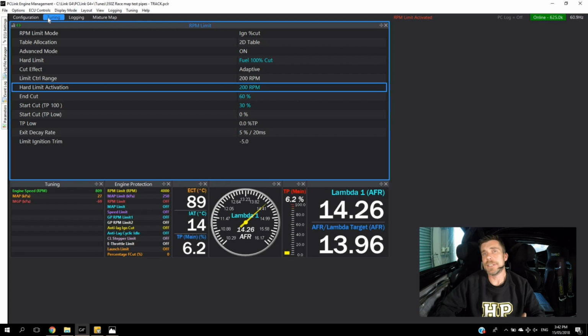So in this instance, it's quite typical to do away with the soft limit that we've looked at there with our control range. We would then instigate just a 100% hard cut right at the RPM limit that the class allows, and then it's up to the driver to control the engine RPM to change gear just prior to that rev cut.